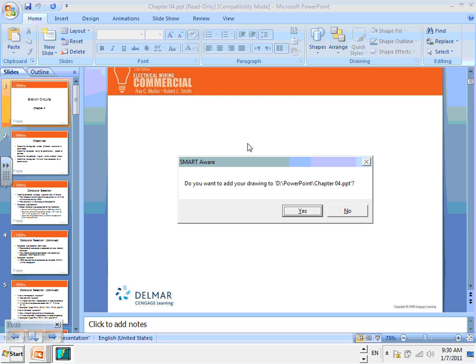And then they divided them, calculated amp. They divided the volt-amp by the voltage, and they came up with 6.5. Everybody knows how we came up with 6.5. Just divide 783 by the voltage. Okay? Then load type is continuous. From what we see, it is continuous. Our receptacle is continuous. Load modifier, that's what I don't like, because he's adding them all.